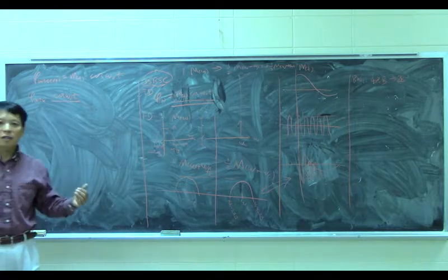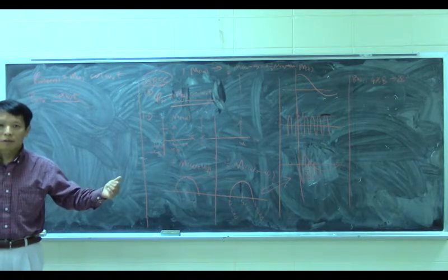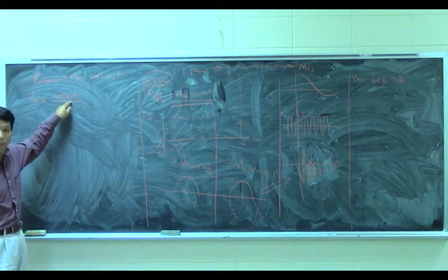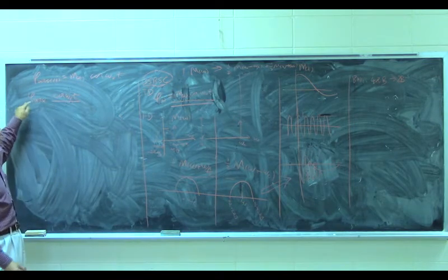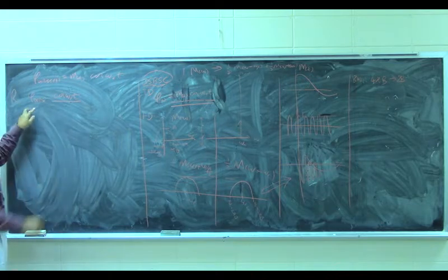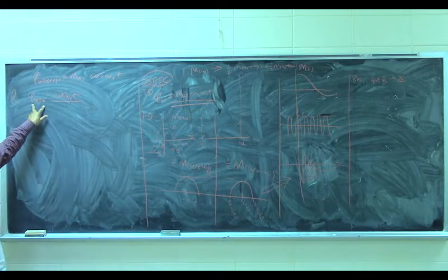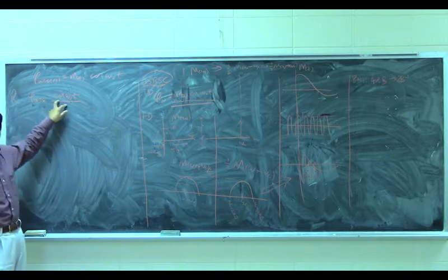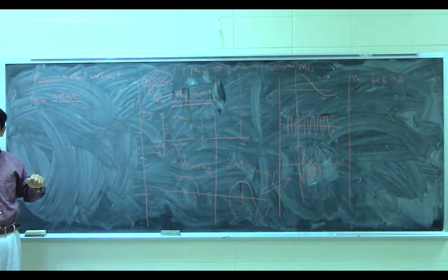What is this? That is the carrier signal at the transmitter. Suppose I know this one, I will use it again at the receiver. So at the receiver side, I will multiply the received modulated signal with this carrier again. Does it make sense?